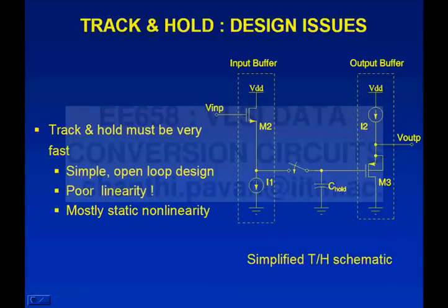So the same thing here, and if you want to maximize swing, you want to be able to swing large amounts here, which basically means that you would like this voltage to go as low as possible. If you want to swing large amounts here, you want to go as low as possible, correct? The maximum you can swing here is on the top limited to VDD. On the lower side, if this goes too low, then this will also go low, which means that this current source I1 will get into the triode region. So the limit is, you want to be able to push this voltage as low as possible in the interest of an increased signal swing.